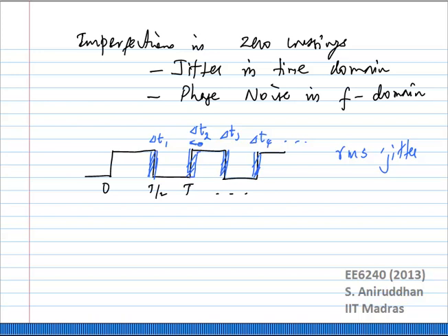Okay, and you are transferring a file, you are worried about the timing. Similarly, maybe a display card, like you have a PCI Express card for a display. It's all the same thing, right? Many of these applications, you are trying to transmit a switching signal from one chip to another, right? In those cases, the switching instants are very important because you are actually transmitting a baseband signal directly. You are not transmitting a modulated signal. You are not upconverting it.